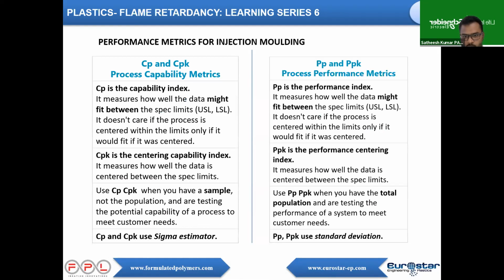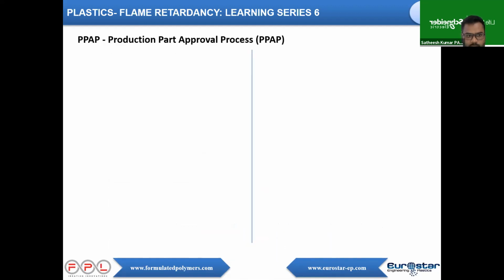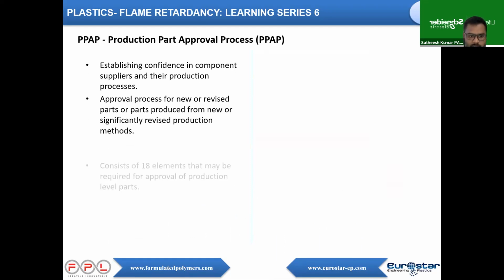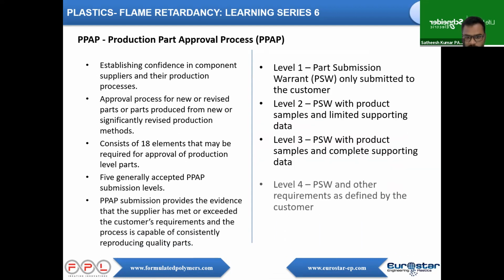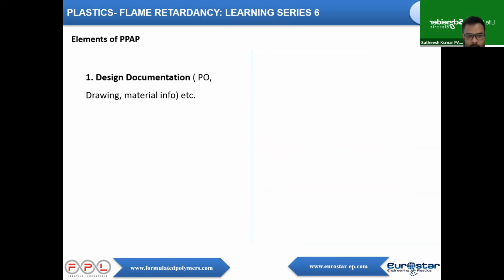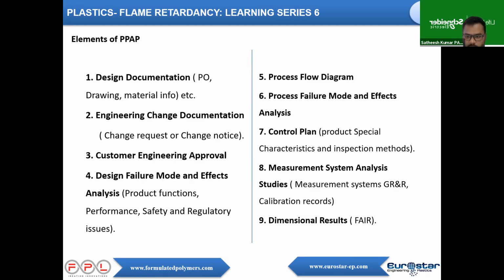Let me show you. Oh, okay, so this is what you have given. I'm going to keep this, and then I'm coming to PPAP. So for PPAP, there are 5 levels of process, and a minimum of 18 different things, or I would say 18 documents which need to be managed. So I will talk about that here: generally, what is PPAP, what are the different levels, and the documentation required. And again, whatever I told on the 18 points that need to be taken care of in PPAP.